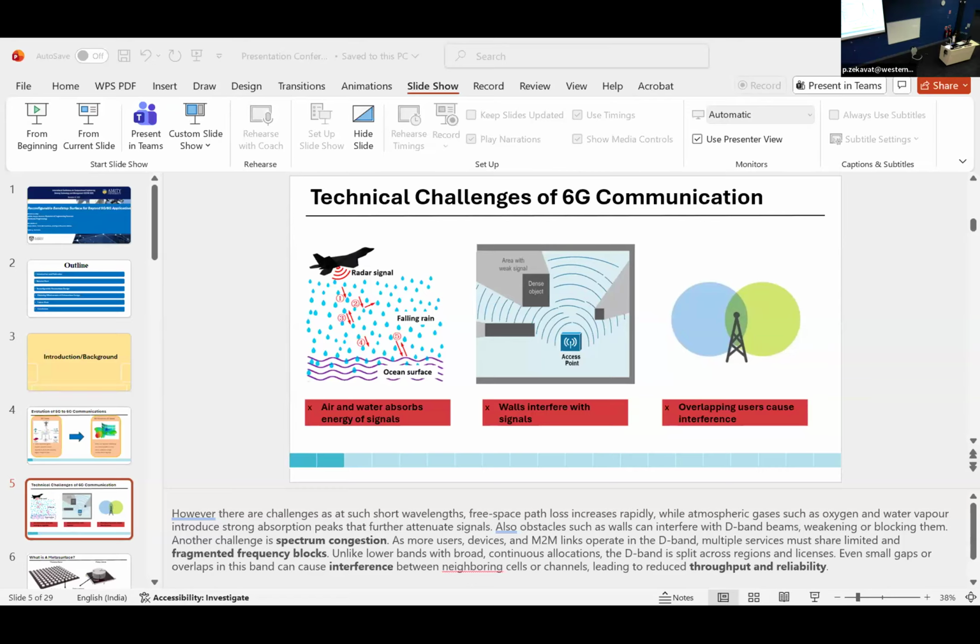So for the results, I focused on the transverse magnetic polarization as this had the greatest tunability range. And so when all the diodes were turned off, the stop band showed a peak at 156 gigahertz, this showed 35 decibels of frequencies blocked.